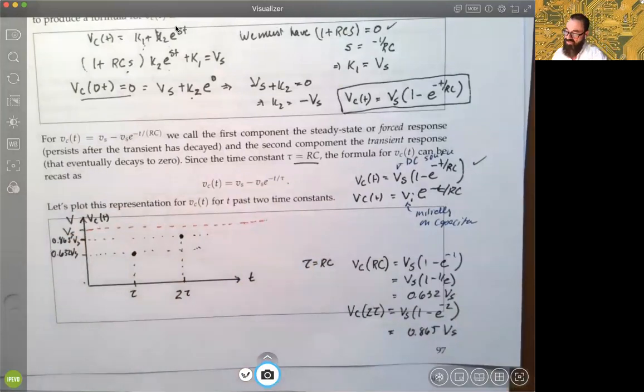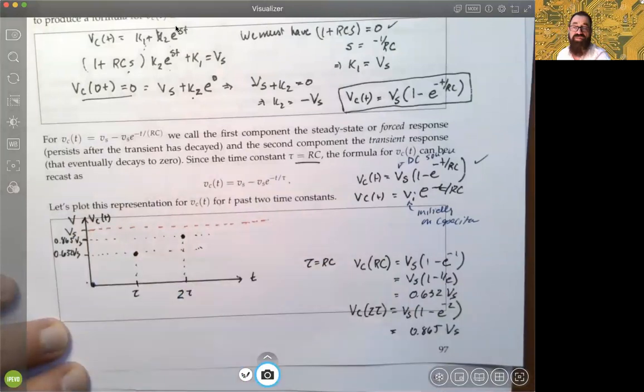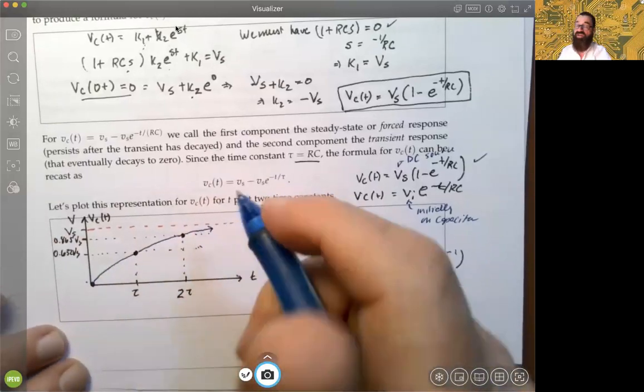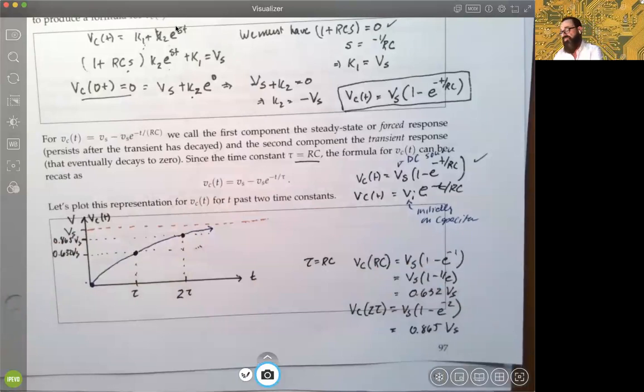And so when you sketch the curve now, again, you have no voltage on that capacitance, 0. Close the switch, and then through time, notice what's happening. It's eventually going to get closer and closer to the voltage that is available, okay, from the Vs. Now, it won't get quite there, okay? It's going to be asymptotic. That should make sense because you do have a resistance, okay? Because of the resistance, if that R parameter wasn't there, then no, that wouldn't be the case, but you've got that resistance. So it's not going to get to Vs, but it could get fairly close to it, depending upon what the values are, okay?